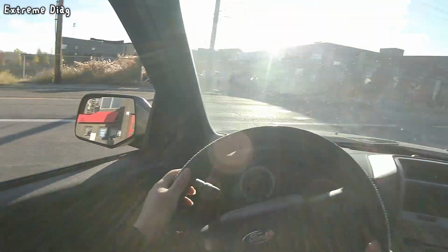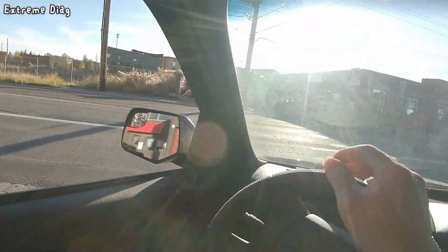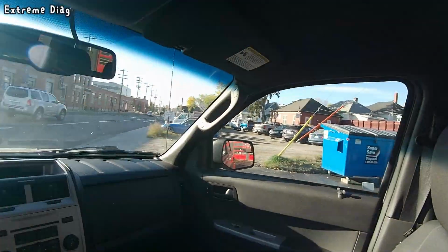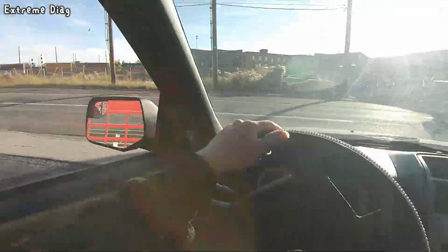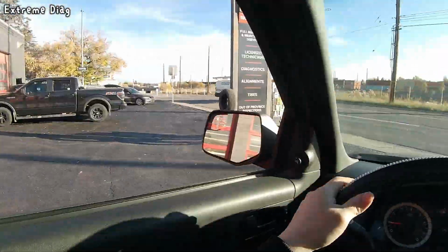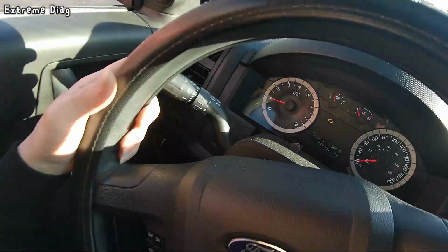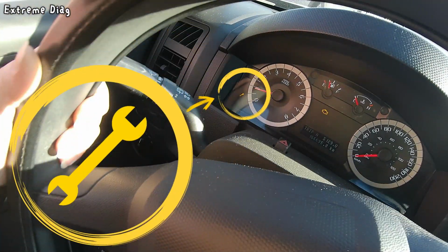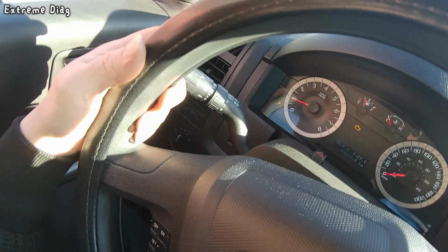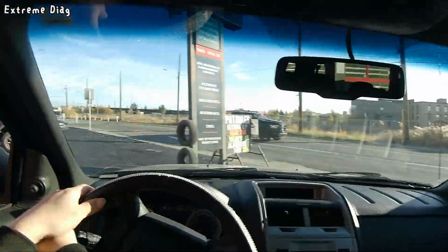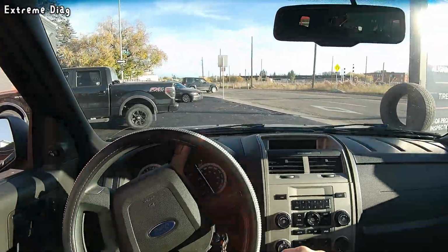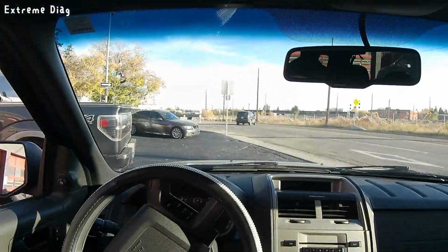Wait a minute, the vehicle is acting strange. It's not moving. I wasn't sure if the symptom would appear on the first drive, but fortunately, I confirmed it before even hitting the road. You can see this wrench-shaped warning light here. This light comes on when the system detects an error in critical components like the throttle body or transmission that could severely impact driving.